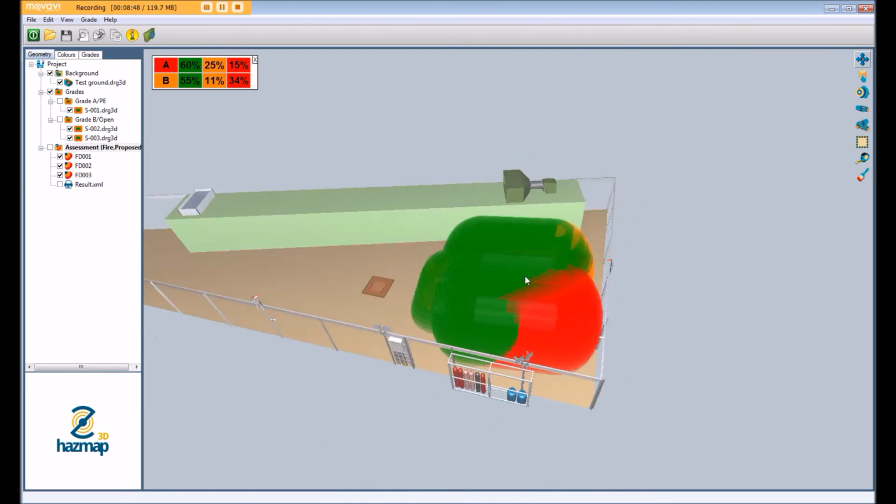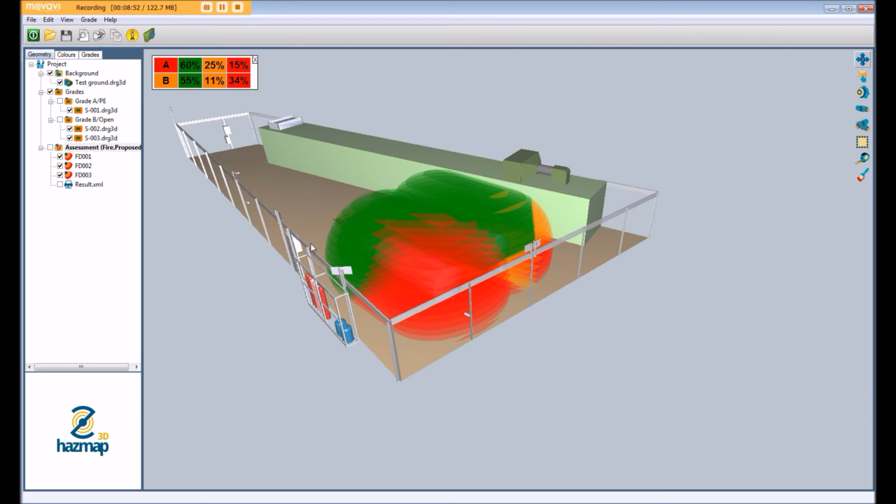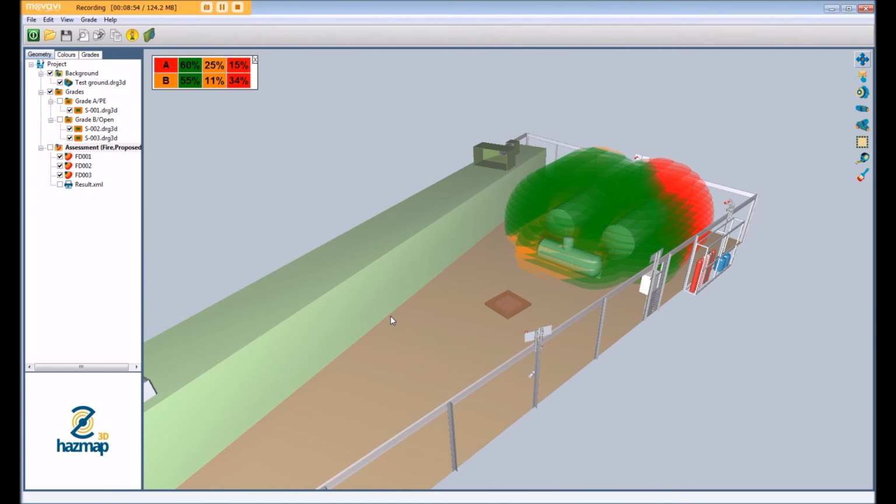Now you can see that obviously we have the introduction of some orange coverage here, which is our 1 out of n coverage for alarm only, because we've changed the voting requirement to a 2 out of n system. And because it's quite a small area, we've not actually seen the impact of the sufficient control action value, but with late alarm, the impact of having 2 different fire sizes within the same assessment. But essentially there are 2 more colours which you could see within the assessment.